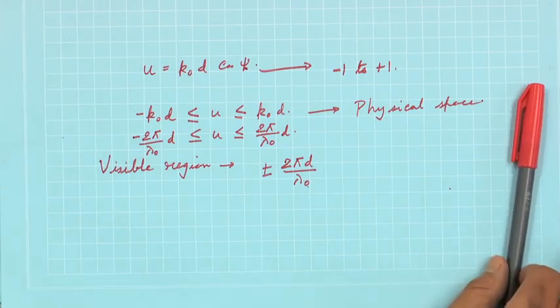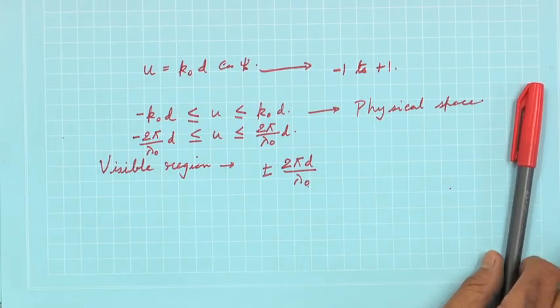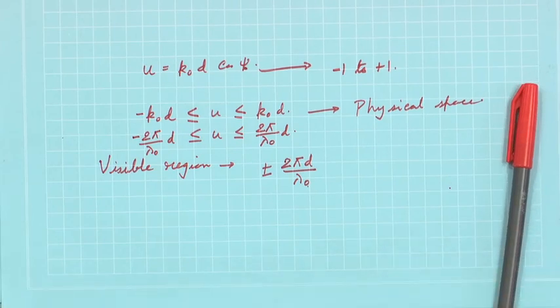There are two special cases of this uniform linear array. I have already mentioned, we have shown the photograph for a two element array. One is called the broadside array, where the radiation or major lobe peaks perpendicular to the axis of the antenna, and another is the end fire array, where the maximum radiation or main lobe is along the axis.